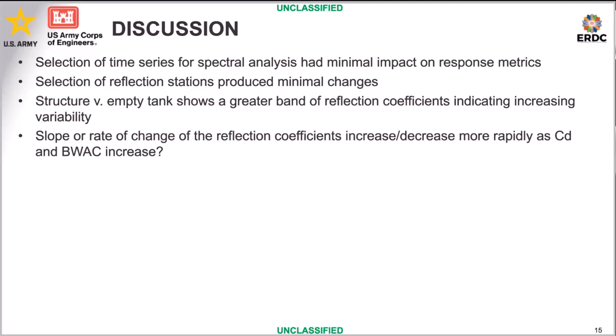is different. So it's either increasing or decreasing. Like, is the BWAC, is the wave reflection and wave transmission response with the permeable layer, with the breakwater layer, is it changing faster or slower than when you have just bottom friction? And that's really towards the answer that we wanted to have, right?